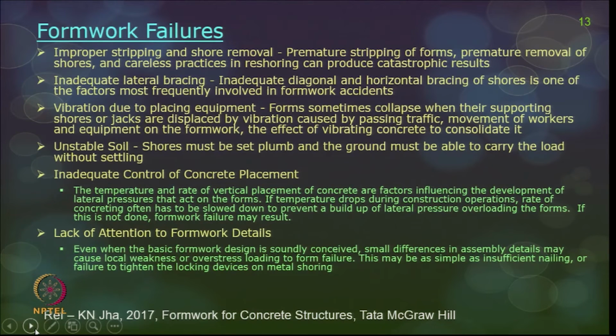Inadequate control of concrete placement. As I said, there is a rate and a temperature variation with which the concrete gets pumped or poured into the structure, and the temperature starts differing. Okay. So, when the rate of placement or pouring of concrete is varying, or when the concrete is poured at a different speed, the temperature also generally varies. This can create an imbalance in the load onto the structure. So, that also has to be kept in mind, and the lateral pressure overloading onto the forms.